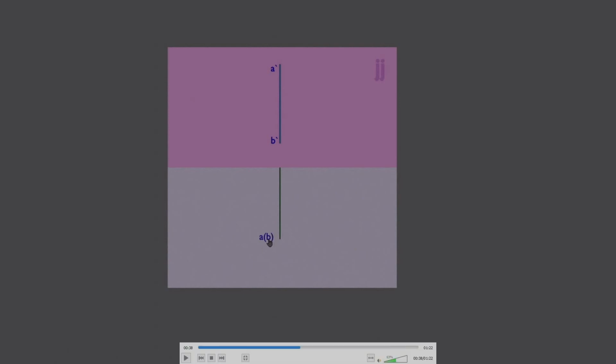It's given like that because you don't see the point B. When you look from the top, when you look from here, do you see the point B? B is just below A, right? So that is why you see only point A. So that is why you give it as A and in parenthesis B. Okay, so this is the orthographic drawing of a line which is perpendicular to one plane. That is, right now it is perpendicular to the horizontal plane and parallel to the vertical plane. Okay, now let us move on to the next topic.